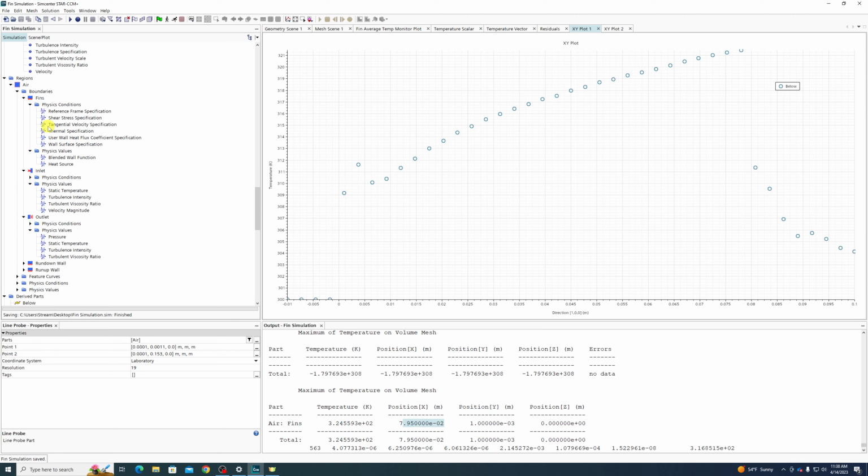So let's go ahead and change our boundary conditions a little bit. We are just adding a fixed amount of heat, right? Well, we can also tell it, no, that's not the way this works. This isn't a heat source. This is a fixed temperature. Fixed temperature of, I don't know, 118 degrees Celsius, give or take. More or less what that is. Click OK.